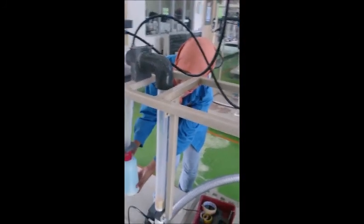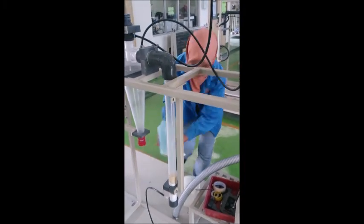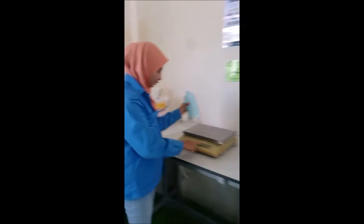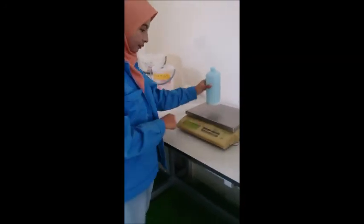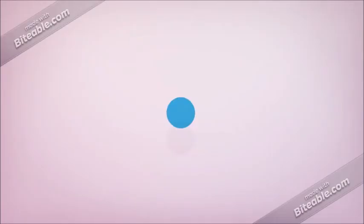Switch off the air blower after the experiment is completed. Detach the feed container and the dust hopper and weigh them separately. Determine the collection efficiency of the cyclone by keying in the weight of sample loaded and collected. Repeat the experiment with the 70mm body diameter cyclone.